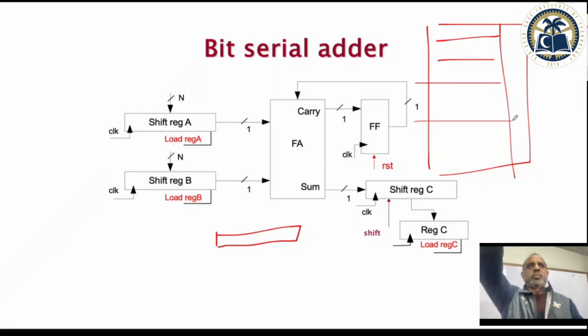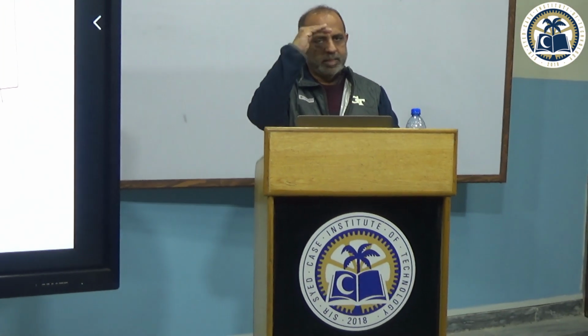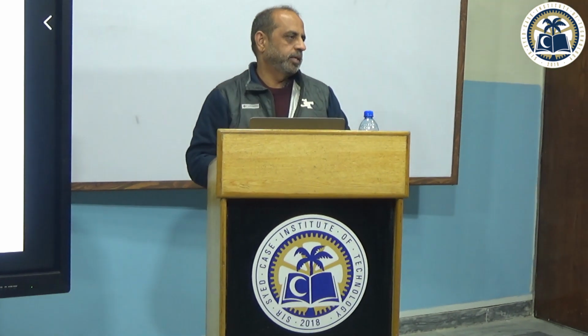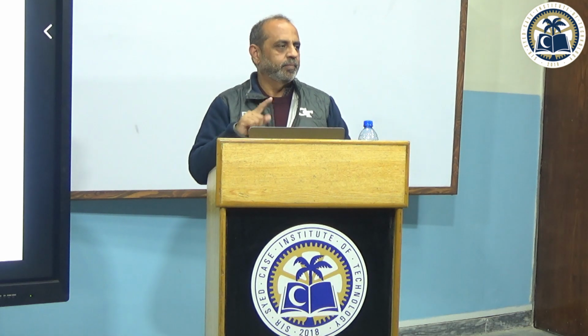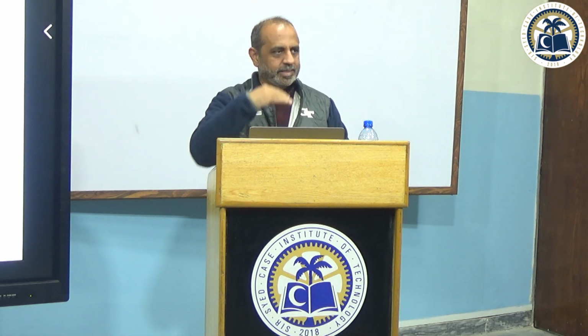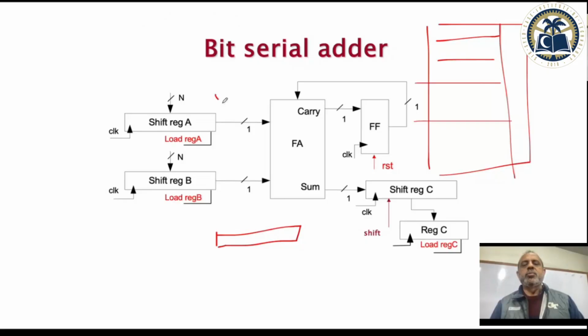My program is going to run in a sequence. Why should I not have a counter? Okay, and all my control signals that I have to generate in a sequence, I'll put in the program. Okay, so next state, if you are sure that the next state is always going to be +1, next, because for example, here is one full adder used to add an n-bit number.